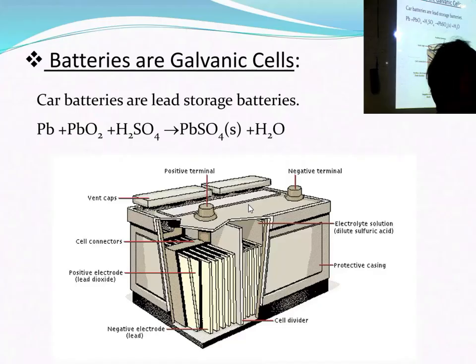We cannot collect that because it is not such a large quantity that it would be economically beneficial. So we allow it to leave into the atmosphere. Every 6 months, 5 to 6 liters of water is getting electrolyzed. That's why you have to refill to get the same concentration back. Otherwise, it will become a very concentrated solution and damage the whole system. Got it? So that is the idea.